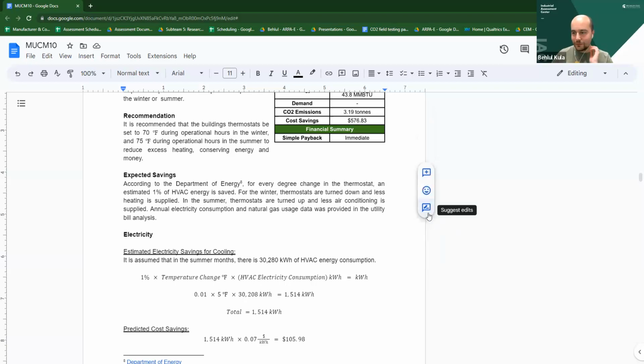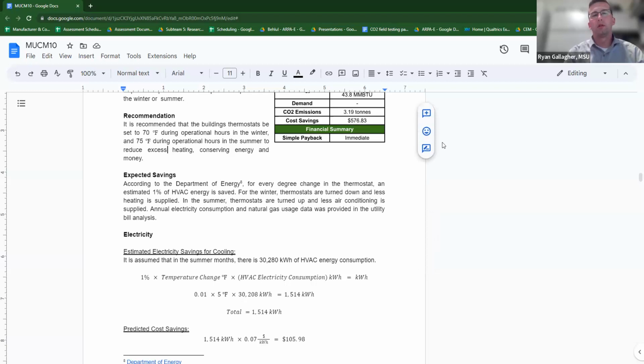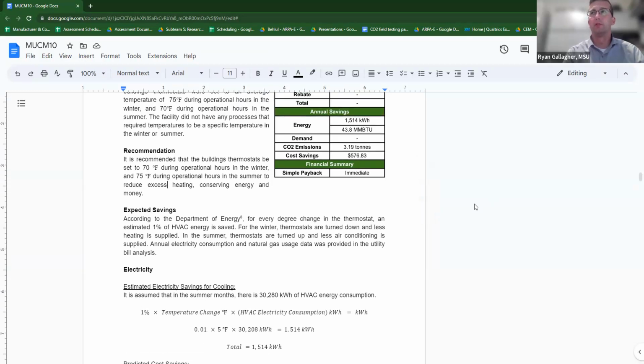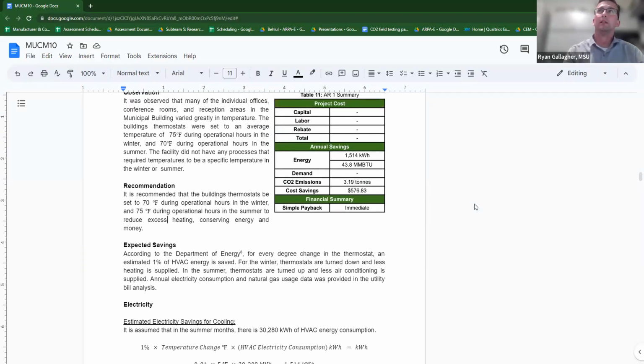And I can give, if you guys are interested, some sequences for how we typically stage hot water perimeter heat versus your reheat system and the duct work. We've come up with some pretty good strategies on how to do that most efficiently to reduce the amount of air volume coming out of diffusers and make sure it's comfortable.